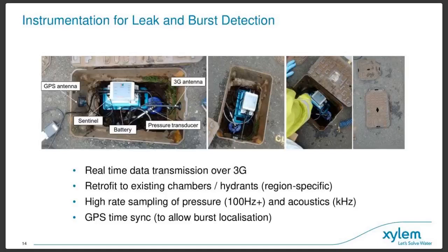It's about sampling pressure at relatively high rates, so hundreds of samples per second, to detect potential burst events, and then also acoustics to listen to the noise in the pipe and understand, is there an elevated level of noise, and is it increasing and indicative of a leak?